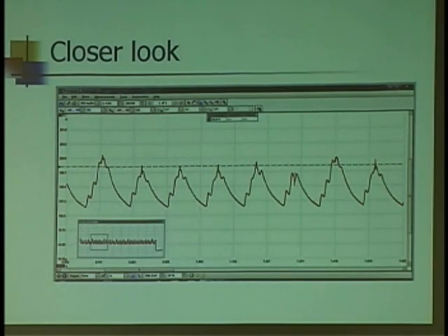Well, let's think about it. What he's asking is that right after the low one, there's a high one. Took more current draw. Okay, so why would that happen? Well, how do most systems identify a misfire? By the crankshaft, right? By speed. So when I have a weak cylinder, it doesn't tweak quite so much. And it did slow down, a few microseconds, not an appreciable amount, but it did slow down. But now that it took a little less to get that one through, the engine's momentarily slowed down, and it's going to take a little bit extra effort to get it sped back up again. Okay.